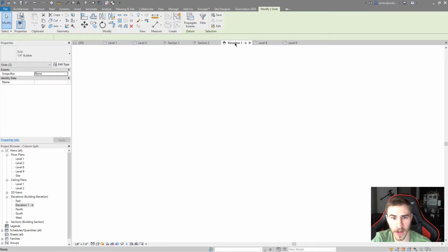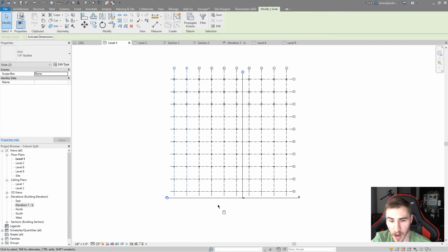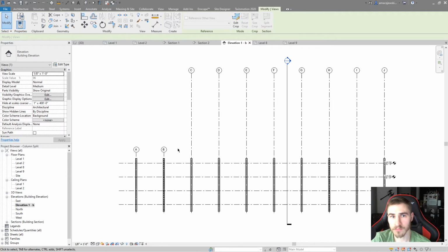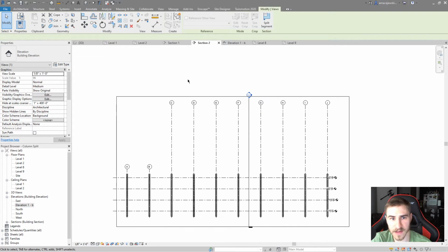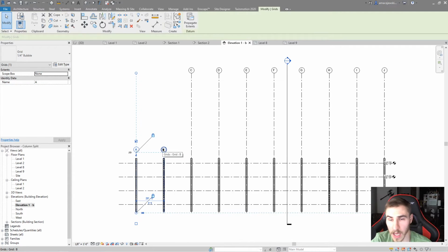So I can come back to this new elevation. You can see that they're pulled down. So maybe this turns into an elevation just for the garage. And so I would pull this back to just show the garage. And if I come back to the garage, perfect. Look at that. So I've got this section that is essentially the same looking as this elevation because they're looking at the same thing, but I'm able to do the exact same thing as far as propagating the extents in an elevation section or in a floor plan. It's just working with these parallel views.